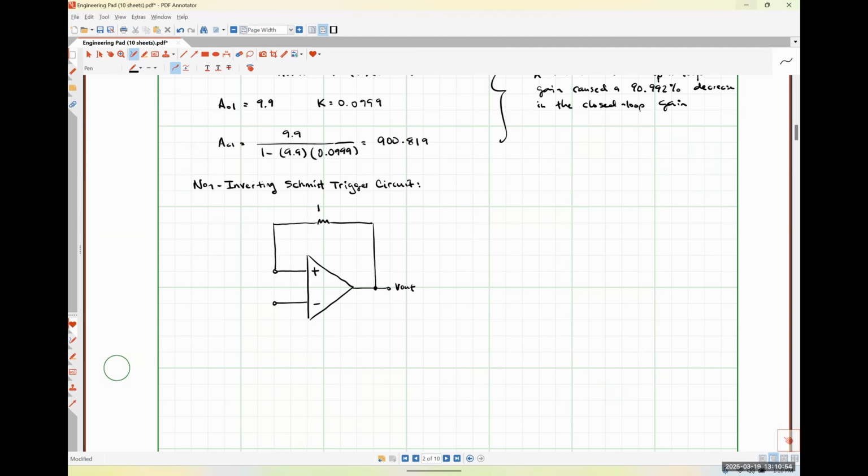I'm going to call this resistor R2. And then between my input signal and that non-inverting input terminal, I'm going to place a resistor R1 like so. Okay. On my inverting input terminal, I'm going to apply my reference voltage, much like I had with my comparator circuits.